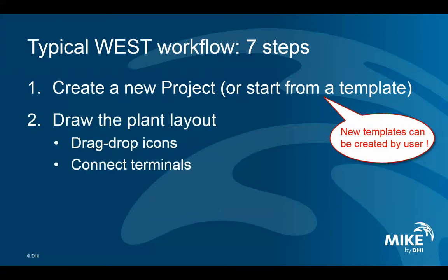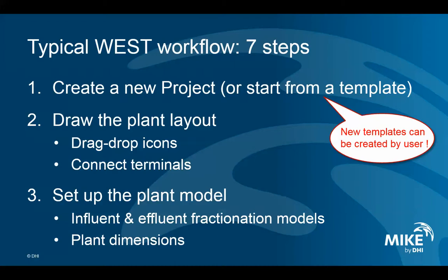I'm then going to assemble the necessary icons by dragging and dropping blocks from the block library onto the canvas and connecting them graphically. I will then go through each block and set up the relevant parameters, such as the size of the tanks, the flow rates of the pumps, temperature of the process, and so on. Most importantly, I'm going to define what is called fractionation and defractionation models, respectively, for the influent and for the effluent, and the influent specifications.